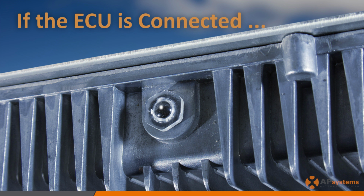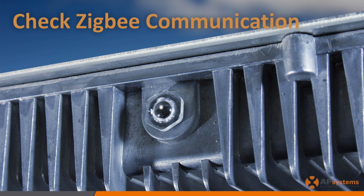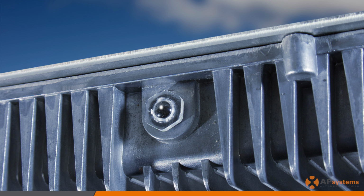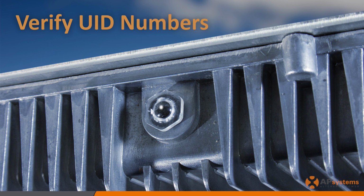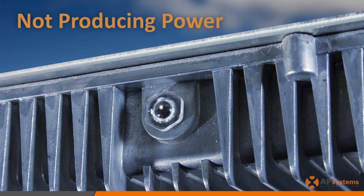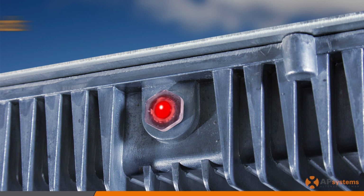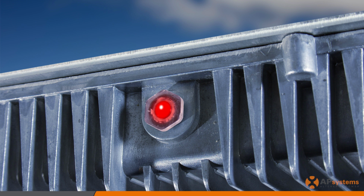If, on the other hand, the ECU is part of the system design, and the inverter's LED is flashing green every 2 seconds, then you'll need to check the Zigbee communication from the inverter to the ECU, as well as verify that the inverter's UIDs have been correctly entered into the ECU. A flashing red LED is an indication that the inverter is not producing power. Check the AC and DC leads to make sure that they are securely connected.